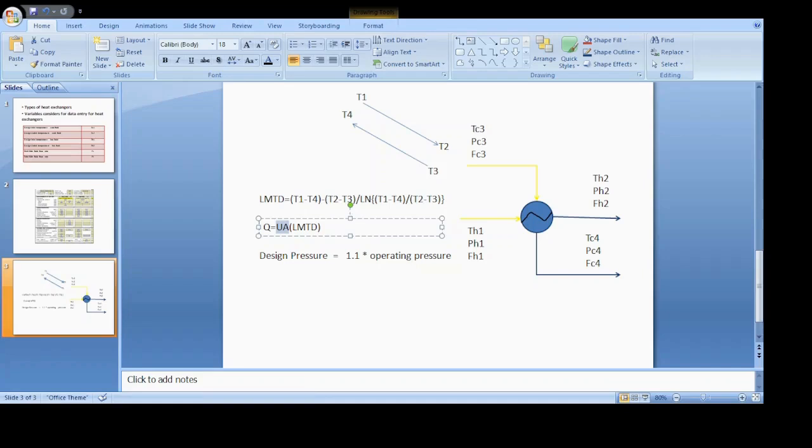Once you checked and it is matched with the HMB, change the mass spec to a pressure spec for the inlet streams of the heat exchanger, and go to the heat exchanger and change the spec from pressure spec to the K value spec while doing the simulation. Once you did all this procedure, then run the simulation once again and check the inlet outlet temperatures and flow rate as per the requirement. If it is matching,